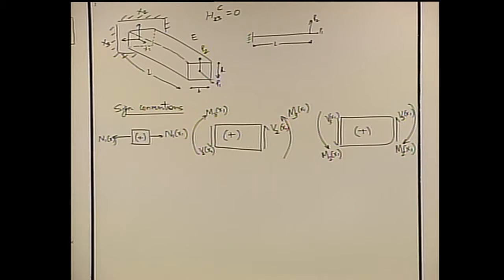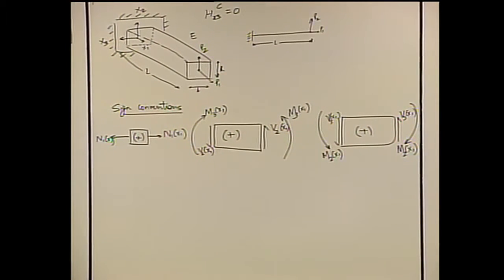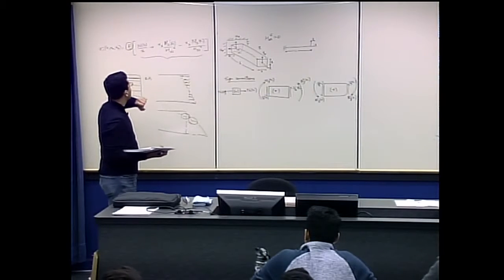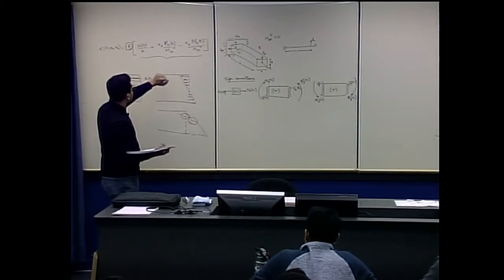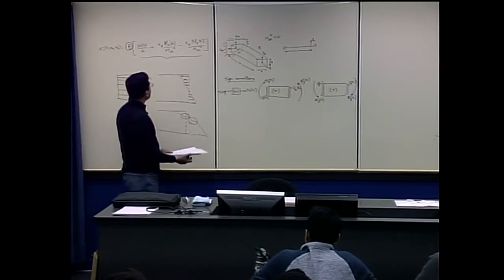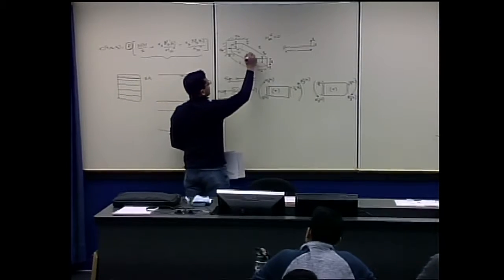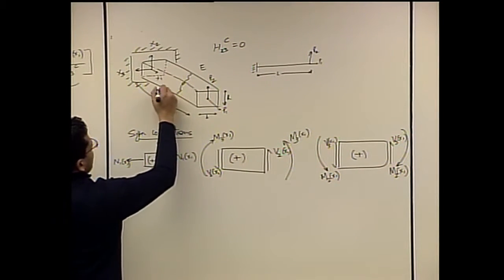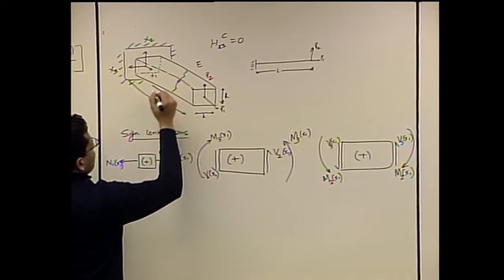So let's evaluate where the stresses are, where the maximum stresses are, and whatever we need to know from this problem. First of all, we would need to evaluate N1 x1, M2 x1, and M3 x1, so that we can substitute these values in this expression. We would also need to evaluate H33 and H22 and S. So let's say we make a cut somewhere in the beam at a distance of x1 from the root.